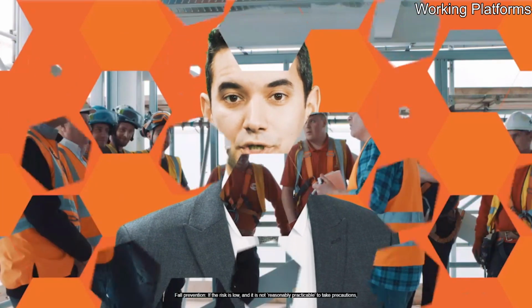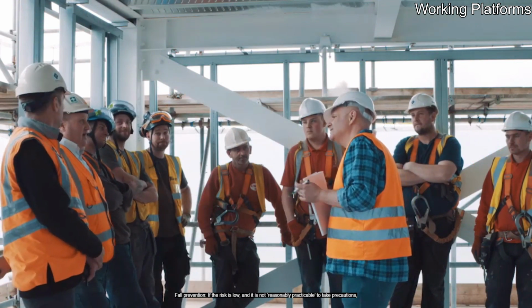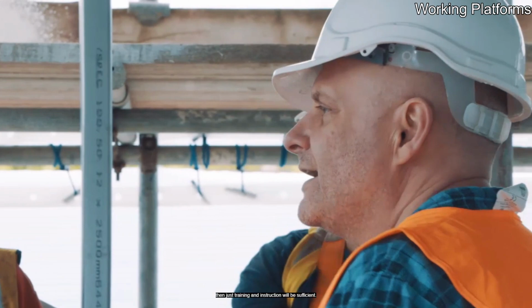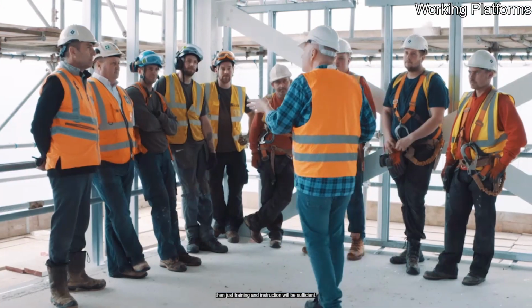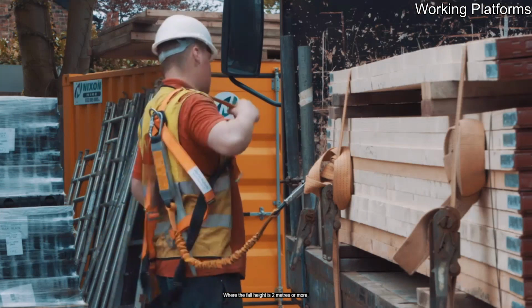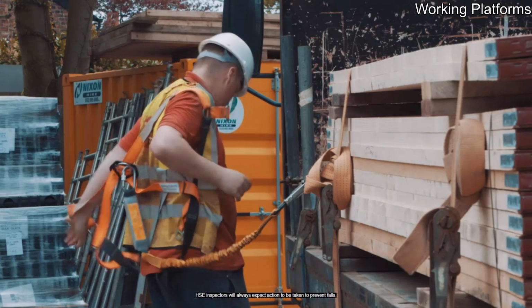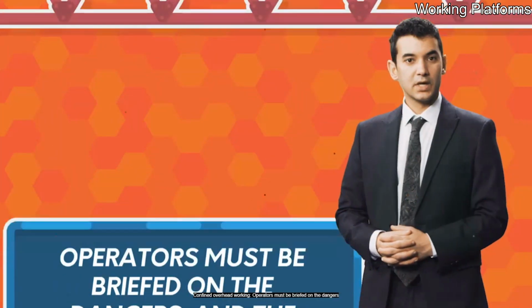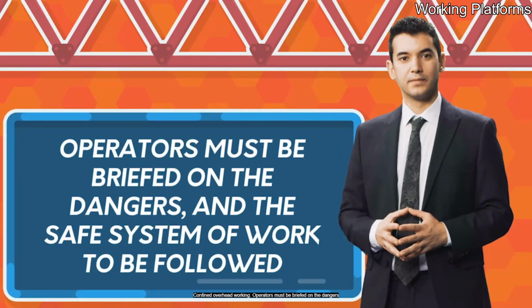There are a number of precautions that can be taken to reduce the risk from MEWP hazards. These include fall prevention. If the risk is low, and it is not reasonably practicable to take precautions, then just training and instruction will be sufficient. Where the fall height is 2 meters or more, HSE inspectors will always expect action to be taken to prevent falls.